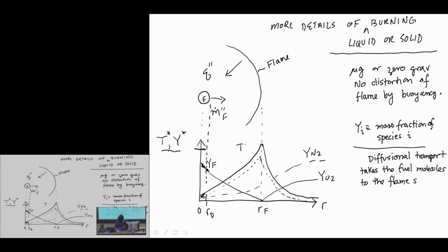And so you might question, well, why would it take it to the flame sheet? Why is there a gradient where the diffusion can act? Well, earlier on we said that, I think we said this, I hope I said this, well, maybe I'll say it now, that the reaction rate in these systems looks like YF, YO, this is sort of a simple description, exponential of minus E over RT. So this is that Arrhenius law.